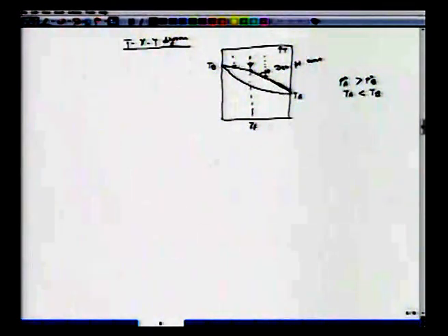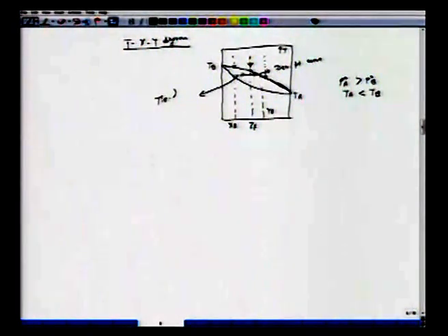All right. So now if we further cool from here, then we will get a liquid and vapor mixture here. We can call this XA. We can denote this as YA. The idea here is that the amount of liquid formed will be in the ratio of this by this. So it's a tie line, and we can apply the lever rule which we discussed in the previous slide.